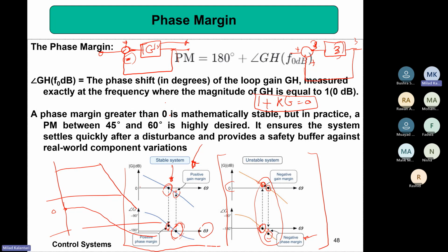But what if the gain is lower than 1, like 0.1? If you had something like 1 volt here, then the output becomes 0.1, and then it goes back to the input as 0.1, multiplied again, dropping. It will not grow, though the sign of the feedback is positive, since the gain is lower than 1. It's not only a matter of the sign, but also the gain.